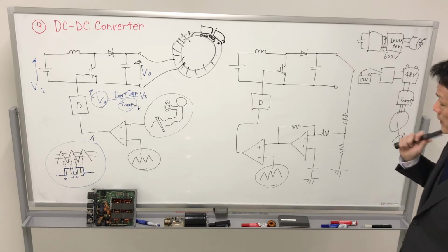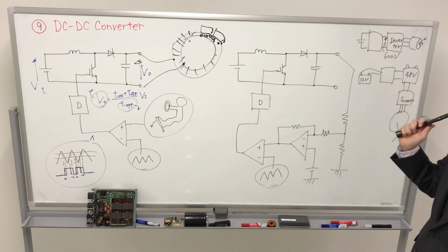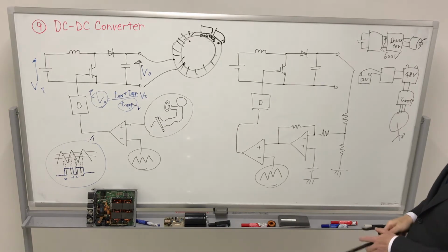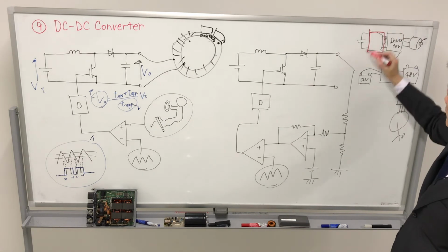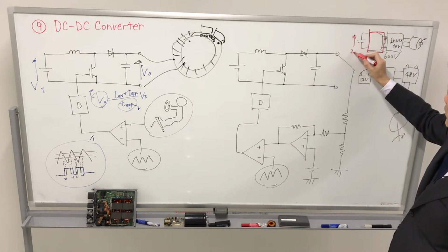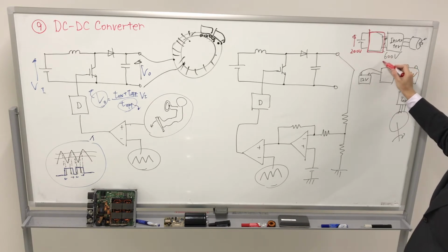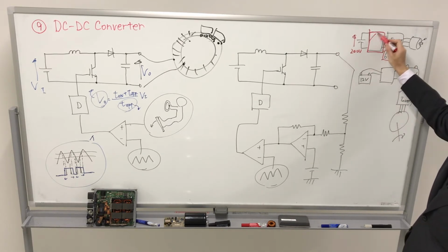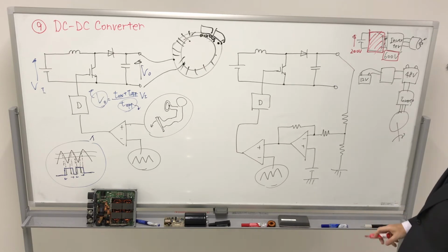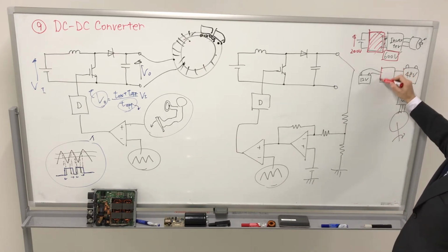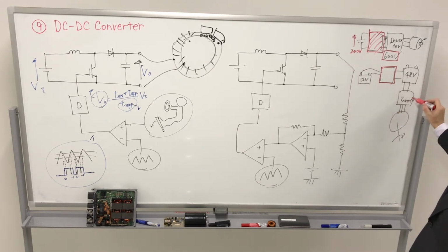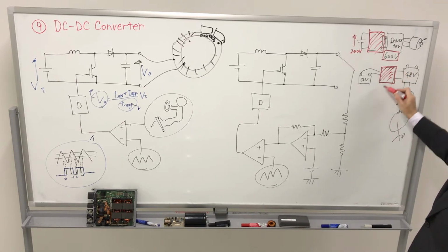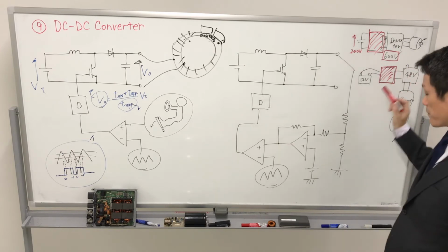However, in the real automotive area, we must prepare the DC-DC converter because the lithium battery is low voltage, but the inverter side requires higher voltage, so a boost chopper is required. For motor driving we require higher voltage, so we require the boost chopper.